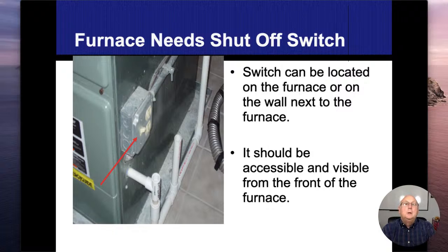Right. Shut-off switches, like I said, they should be in the same room wherever the furnace is. I kind of like them mounted on the furnace myself. It kind of verifies that the furnace is also grounded, when it's connected to our conduit system and our junction box and so forth that's on there. To me, it's just a smart way to protect it.